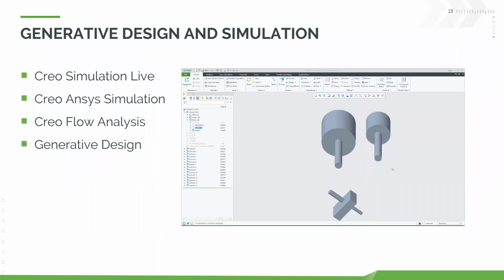You can do this before you start into a generative optimization. Essentially do this like a sanity check, just make sure that your loads and constraints all look right, and then do your generative run. Allows you to avoid spending time on the wrong things, really put the focus back on doing just what you want in generative.